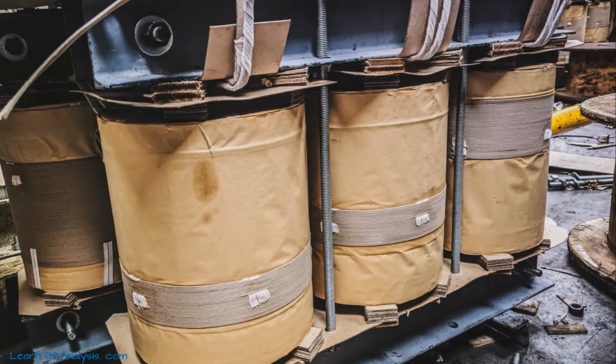But what happens when the paper insulation in your transformer starts to break down? This is also seen when a high temperature fault is occurring, which is why we address it here, as it can burn the paper or cause carbonization of the paper. This is where carbon monoxide comes into play.